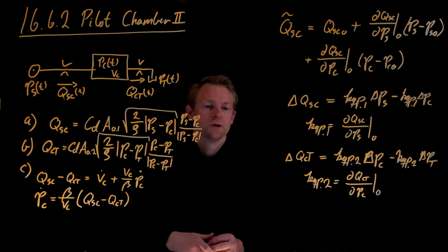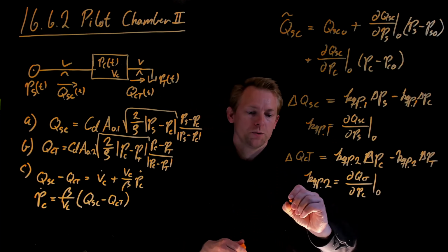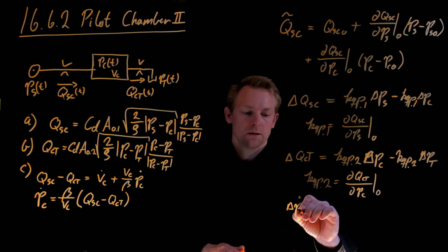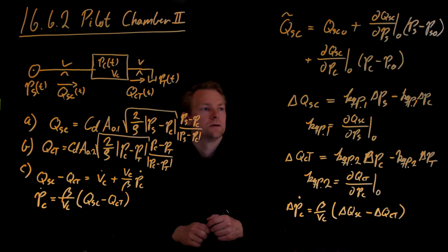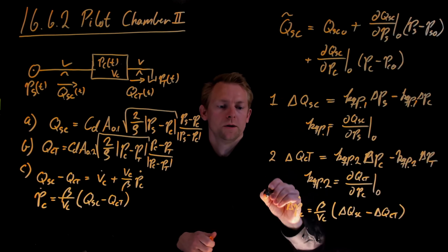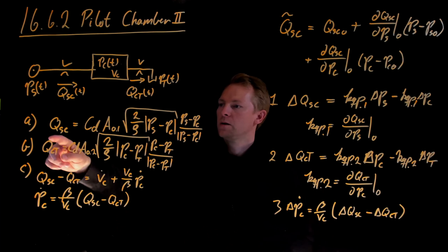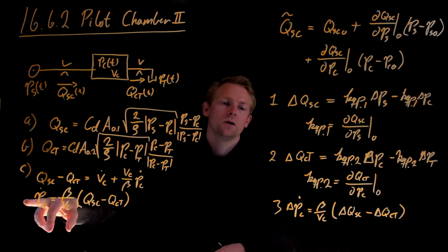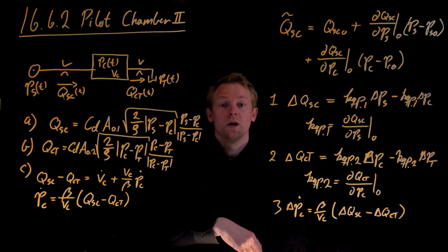We can put it in change variable settings like the one that we have here if we want to, but it is already a linear model. So the linear equations that we have are the ones up here, here, and here. That is our linear model. So we have the time domain model with these two and the later one down here. That is our time domain nonlinear model, and here we have a time domain linear model.